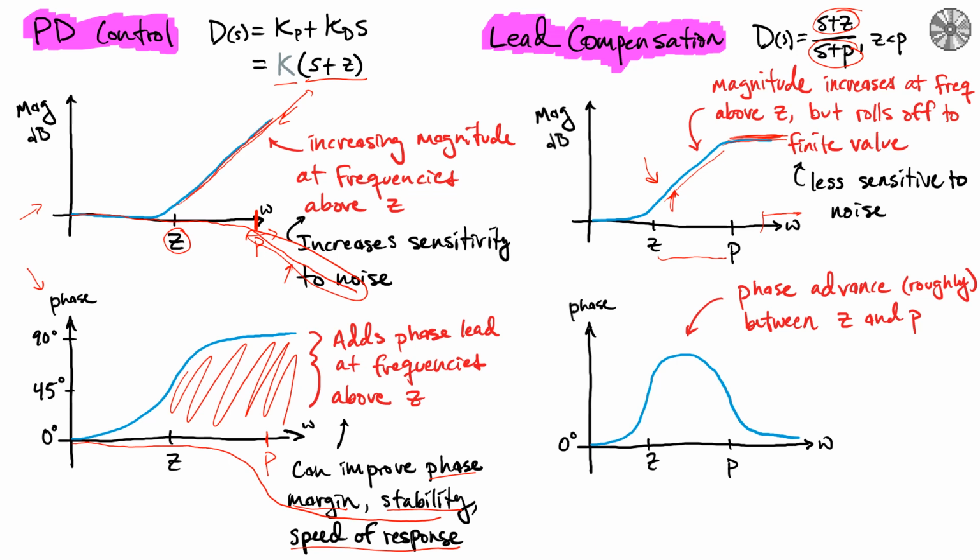So we start to get growth of the phase in the positive direction because of the 0, and because it happens first as we move from 0 to positive, greater and greater values of omega. And then this dip in the pole, that downward trajectory, subtracts away the positive part that the 0 added, leading us back to where we started, near 0.